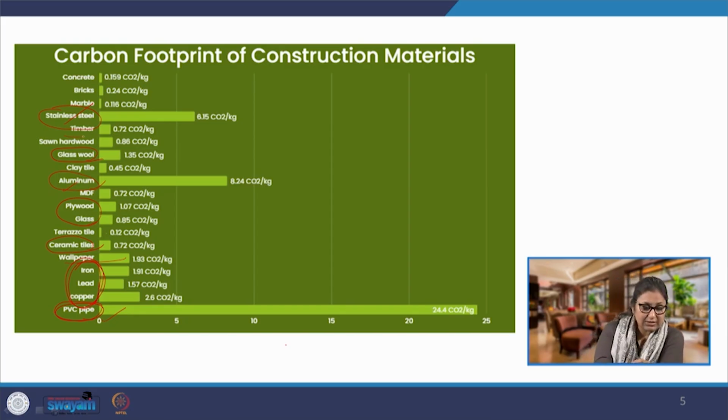So, if you look at this number here, we will see that timber is still having a higher intensity. That is because the wood that is being procured is being seasoned in industries. We keep them in these seasoning chambers for several days, where there are alternate cycles of heating, cooling, and then spraying them with different compounds, different types of oils and all, so that they are seasoned well.